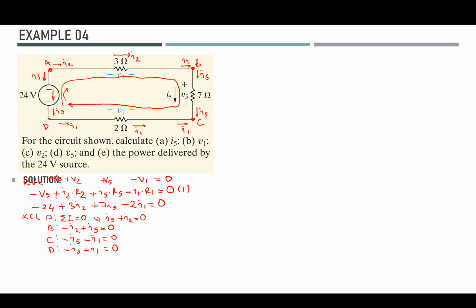From here, I need to bring all my unknowns into one unknown so that I can solve the circuit. These equations coming from KCL will help me to transform this set of equations into a solvable one.